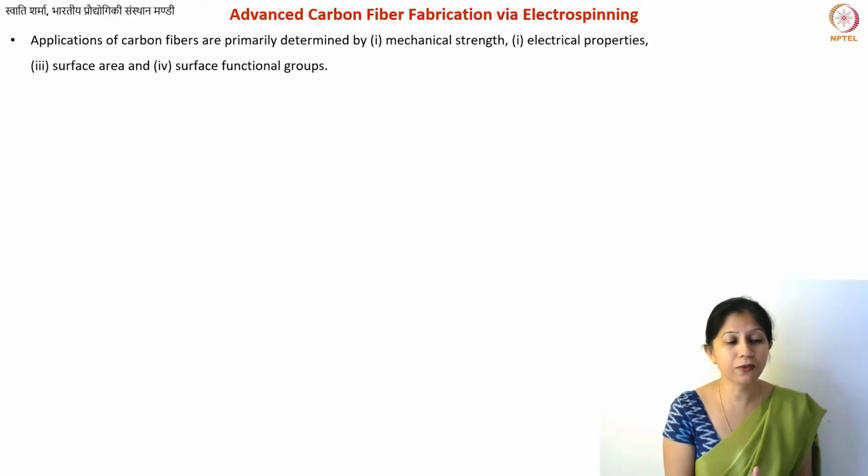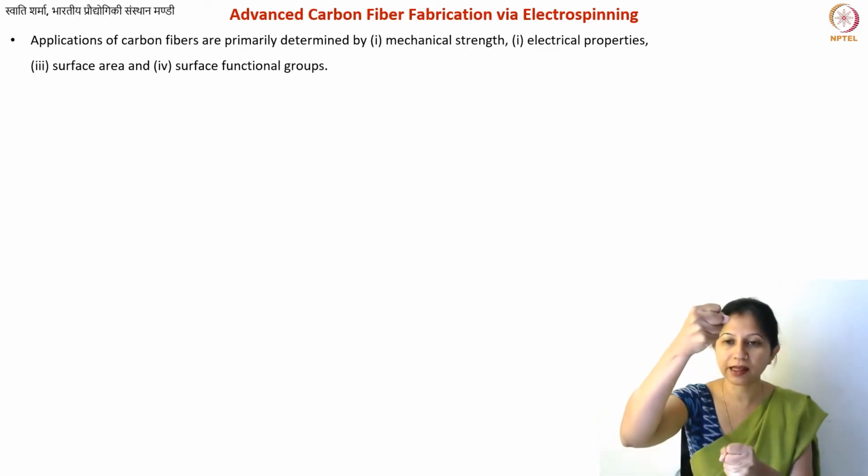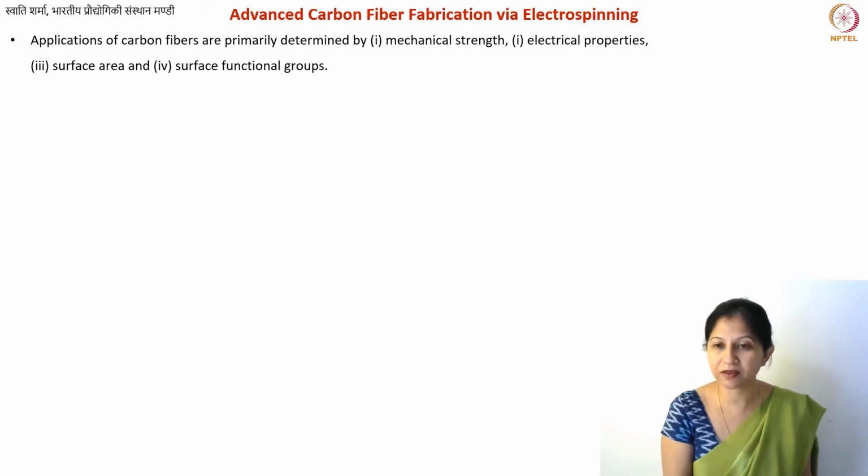So first of all, we test the mechanical strength of our carbon fibers. For manufacturing applications, you will typically not test the mechanical strength of individual fibers, because you're almost always using them as bundles or ropes. So for these threads, ropes or bundles, whatever you call them, whatever the required diameter of our bundle is, we take that bundle and test its tensile strength. Compressive strength also becomes important, but primarily tensile strength.